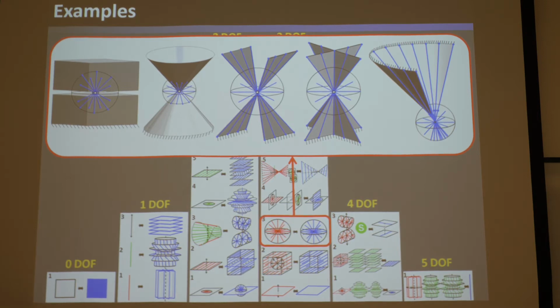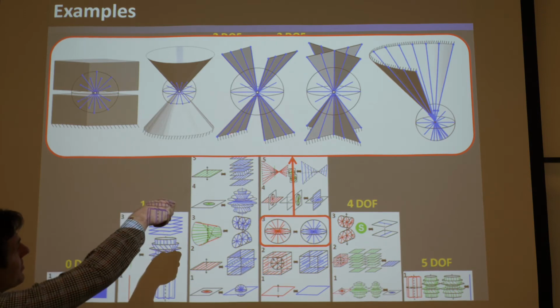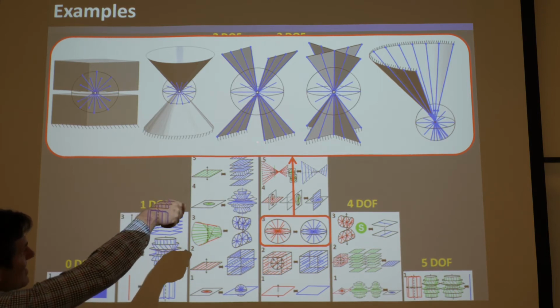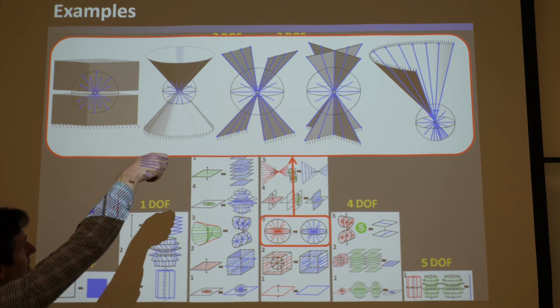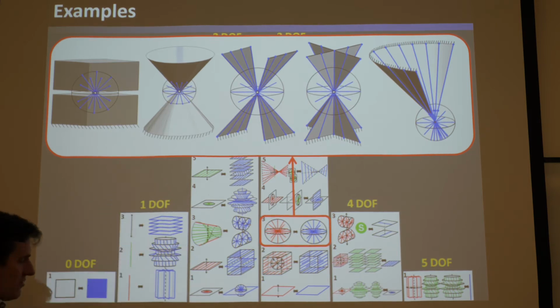Okay, and so this one, the two bodies that would join would be this and this would have to join the same body, ground. You can see it's thatched. And then this top and this top right there, they'd have to be joined to the other body, okay, of the two bodies. And if it did that, it would be considered a single element because it's fused together in the center, and it would have an order of constraint of 3, and it would move like this.